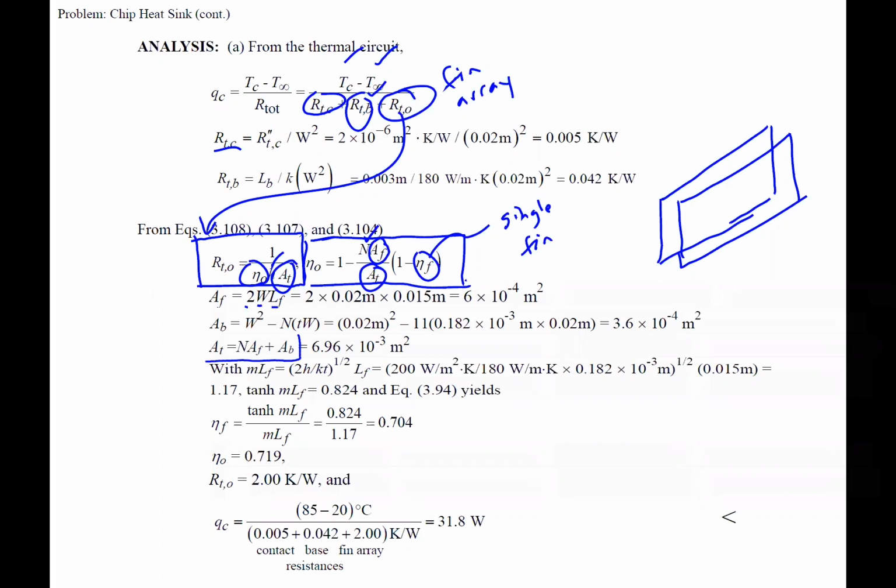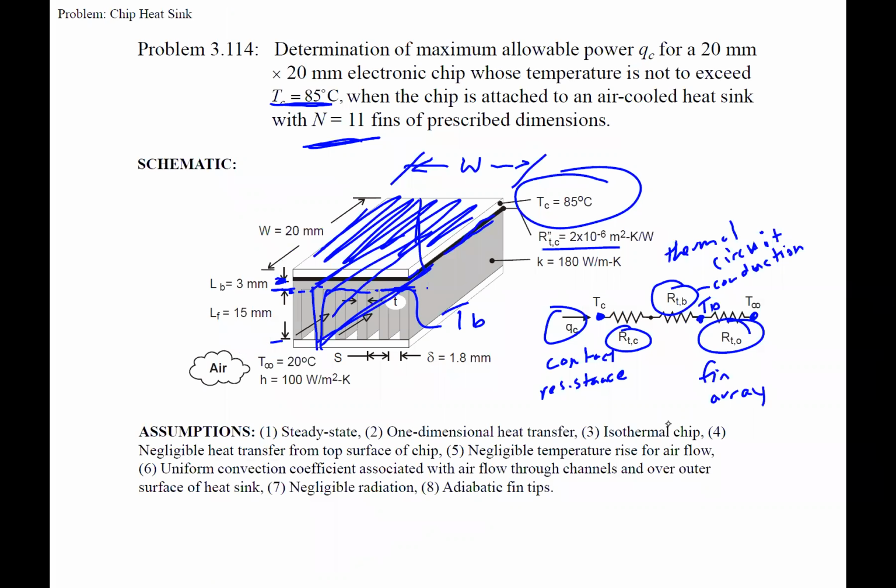And then the total area is, again, all the fins. So that's it right here. The total area is single fin times the number of fins. So that gives all the cooling area on the fins themselves. And then you have that exposed base. What's going on in between, right?